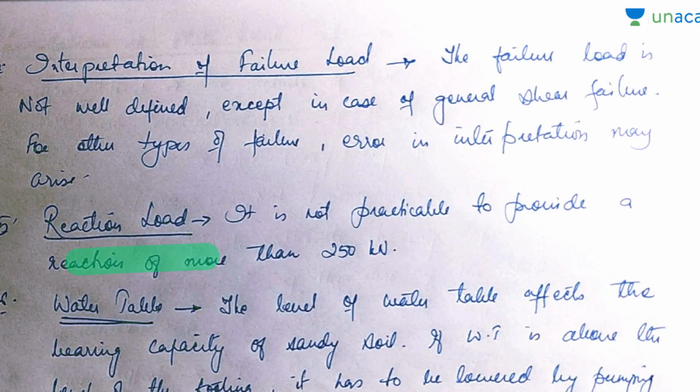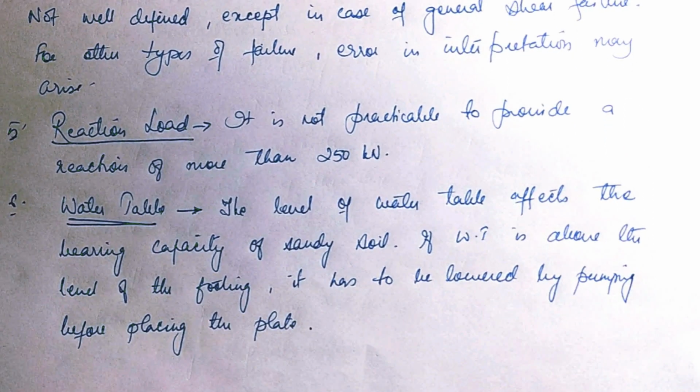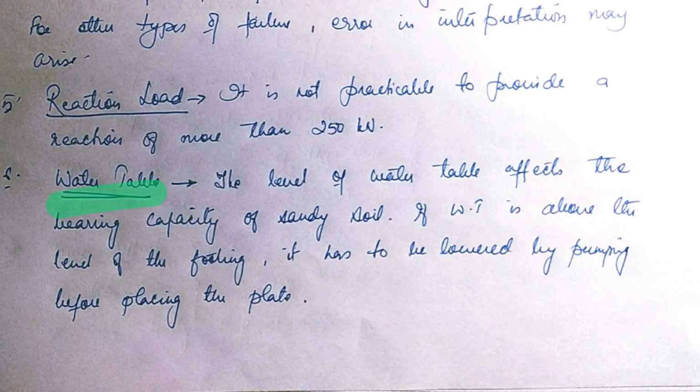Then we have the reaction load. It is not practicable to provide a reaction of more than 250 kilonewton. Hence, the test on a plate of size larger than 0.6 meter width is difficult. Then error may arise because of the water table. The level of water table affects the bearing capacity of sandy soil.